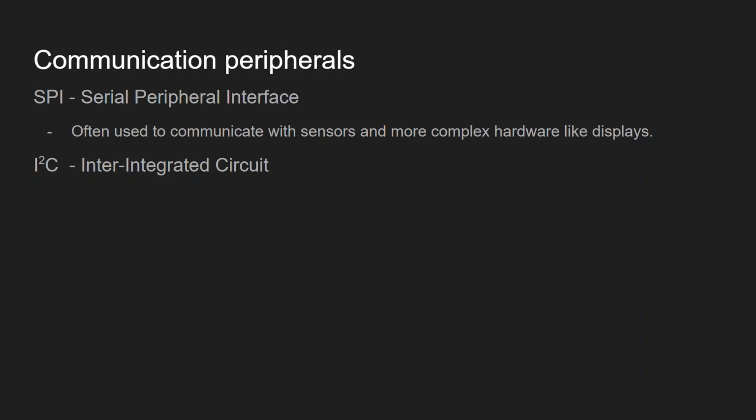The I2C reference design has a 7-bit address space. The I2C bus has multiple modes of operation with maximum transmission speed, but most microcontrollers only have standard mode, 100 kilobits per second, and fast mode, 400 kilobits per second.